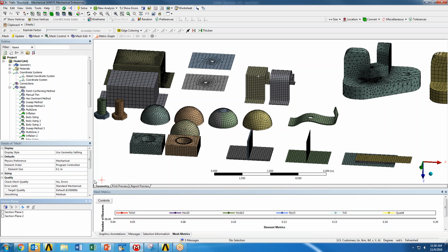Generally, the process I will take is, if you have the licenses available, I'll have SpaceClaim open in one window, and then I'll have Mechanical open in another. And I'll be doing my work in SpaceClaim on a single part, right? Kind of just reducing that geometry to the point where I want it. And once it's done on that single part, I will update Mechanical and just mesh that part just to see that the refinement and reduction that I did on that part achieved what I wanted it to. And if it did, great, and I can move on to the next part.